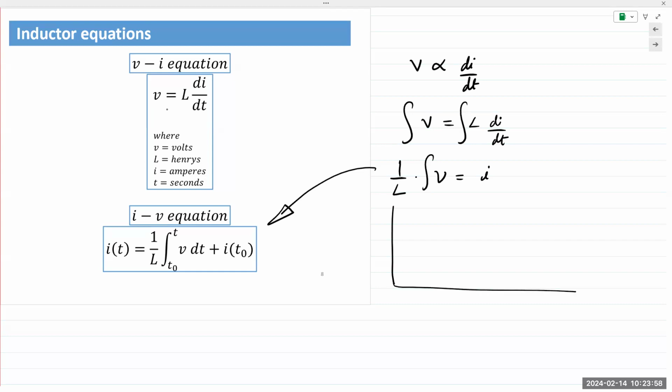For an inductor, we always talk in terms of input current. Current is being applied, which causes a voltage to appear across the inductor. For a capacitor, it's the opposite. For a capacitor, we talk in terms of voltage, so applied input is always a voltage. On the x-axis, we have time. On the y-axis, we have either voltage or current, doesn't matter.